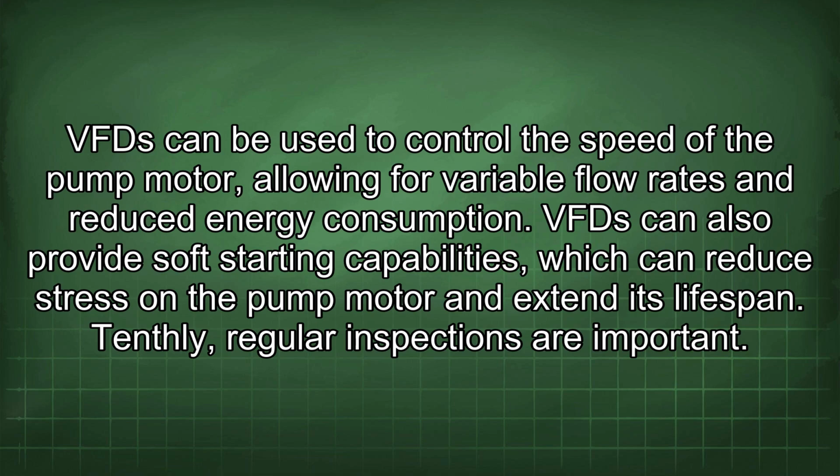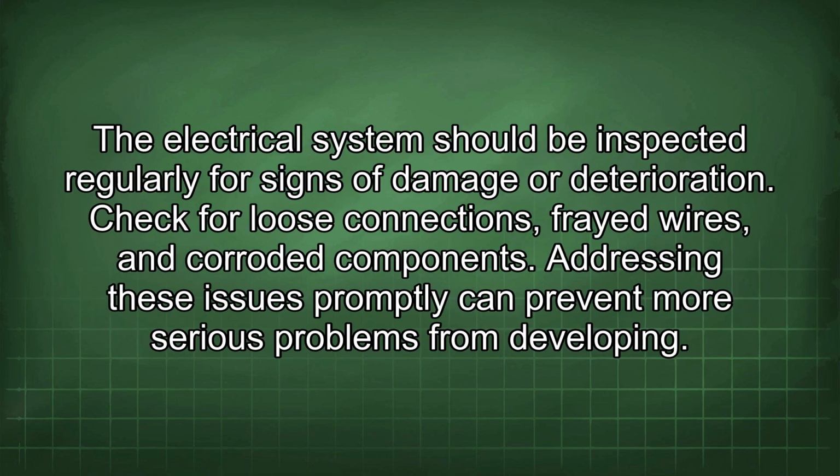Tenthly, regular inspections are important. The electrical system should be inspected regularly for signs of damage or deterioration. Check for loose connections, frayed wires, and corroded components. Addressing these issues promptly can prevent more serious problems from developing.